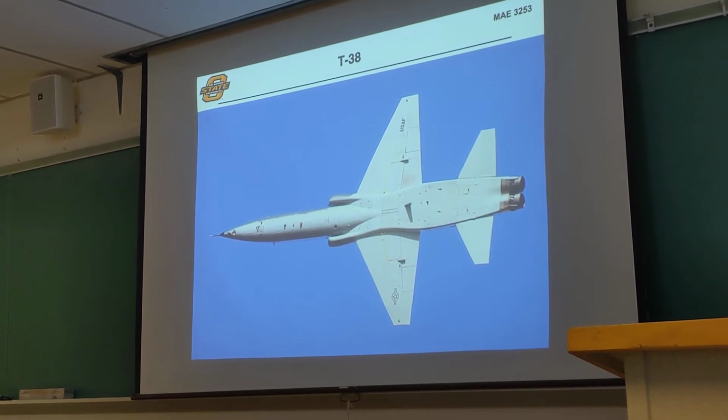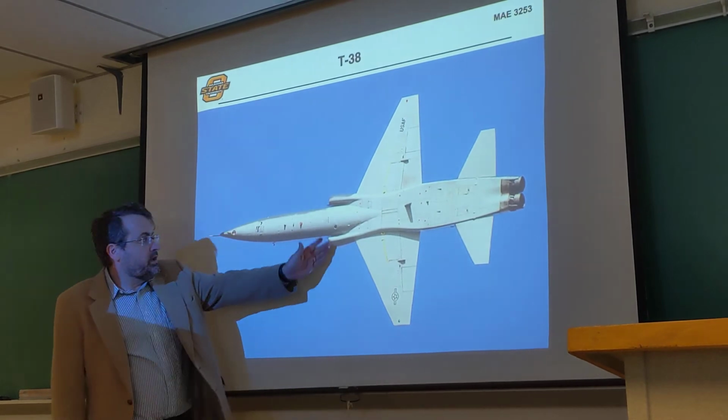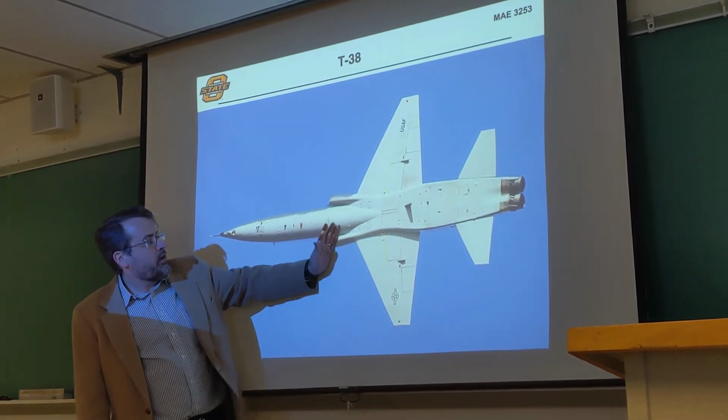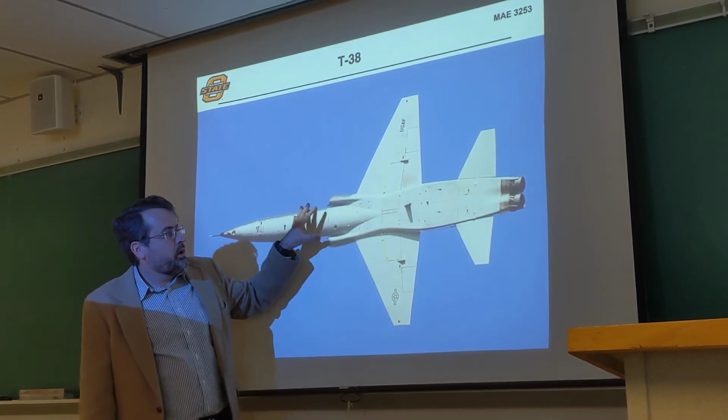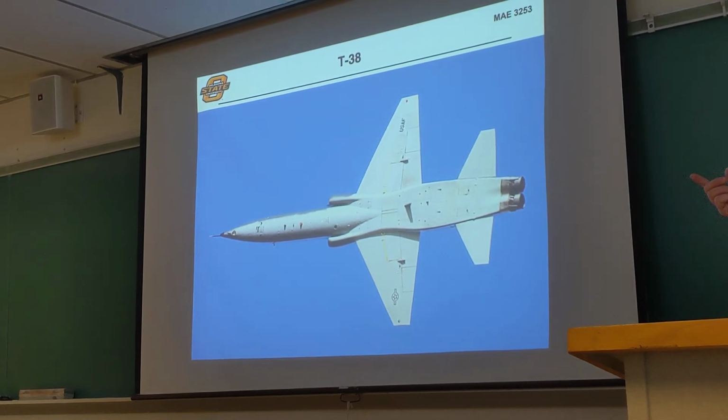And you can see what they've done here with the fuselage. Notice, again, they have the inlet, so you end up having a little bit of a jump in your overall cross-sectional areas. You have the inlets here. They've done a really nice job through the process of waisting that waist down to minimize the impact of the overall compressibility as you go through the process. Doesn't really save anything on the subsonic side, but it really makes a big difference when you're in that high subsonic and transonic regime. So that's kind of the best example.